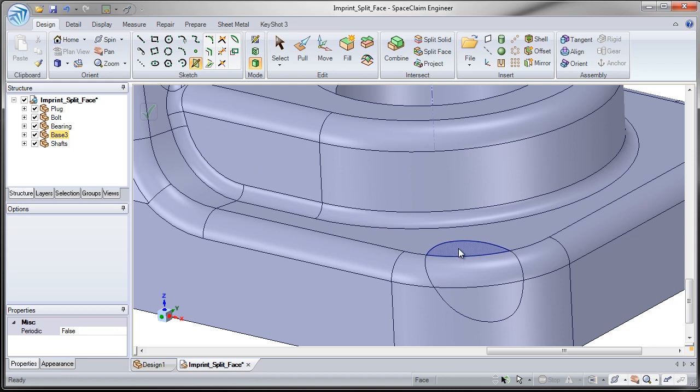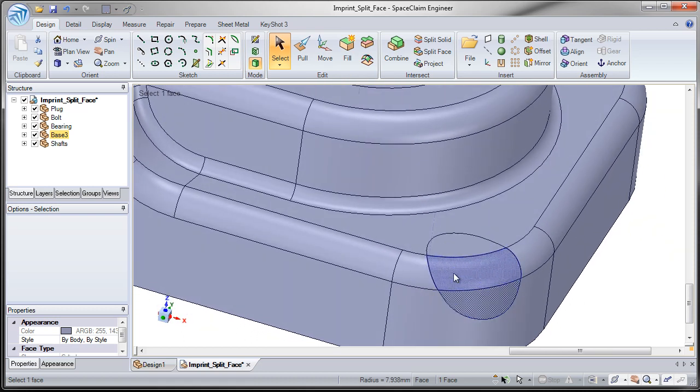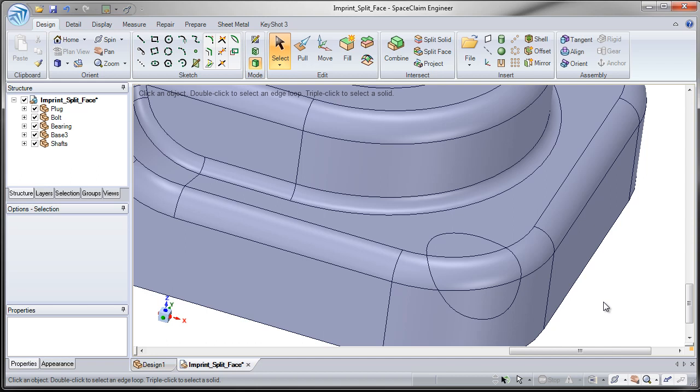That splits these three faces on the model. So now you could apply this for maybe a drop test. You might want to split this region up. You just might want a higher mesh configuration on this area. Or maybe we're applying heat to only a certain portion of the model. Notice this technique is probably the least precise of the techniques and methods I'm going to show you, but it lets you really quickly split a face.